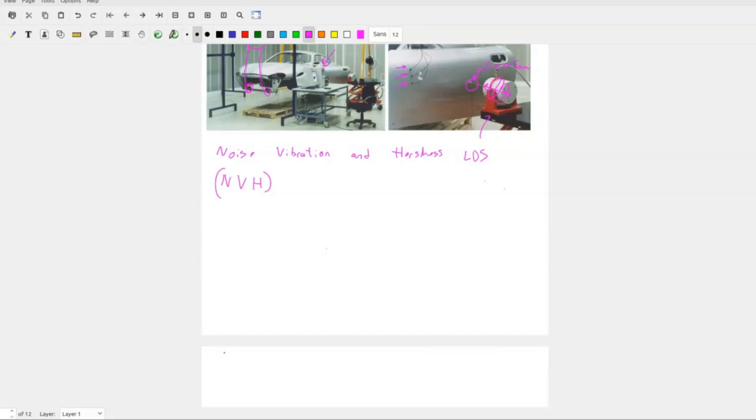Mode shapes are a bit confusing, so let's put on a conceptual hat and try to understand what mode shapes are. First of all, they are not the displacement of the system. That's a common mistake to make, right? People like to think that mode shapes are the displacements of the system. No, rather they describe the configurations into which a structure will naturally displace at a given frequency.